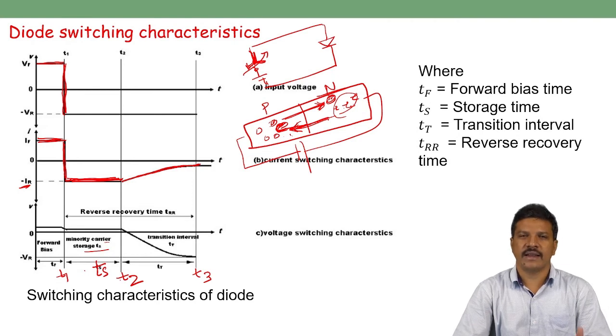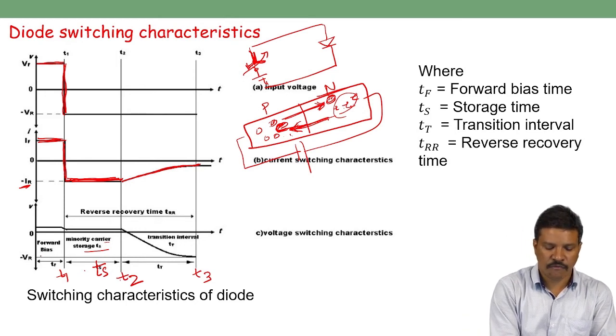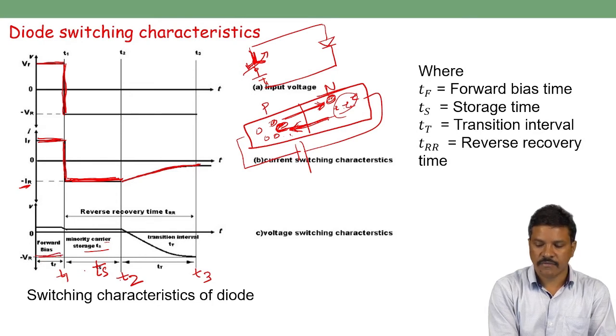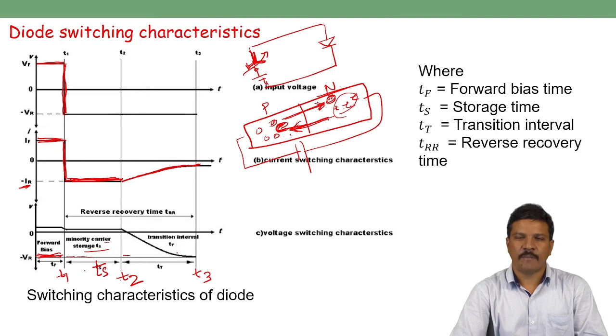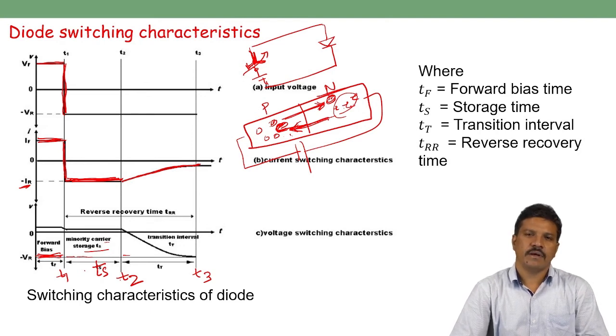But in practice, diode switching has different timings, like forward recovery time and reverse recovery time. Most of the time we can neglect forward recovery time, but we cannot neglect reverse recovery time in practical applications.